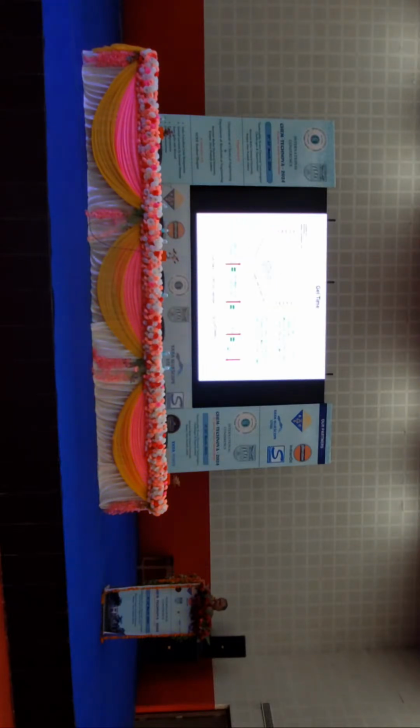Next one, please. Here we obtain gel time, when the phase change is happening from liquid state to gel state. You can see that when the catalyst proportion and accelerator proportion increase, the decomposition of peroxide, which is the catalyst, increases, and the crosslinking increases, because of which the gel time decreases. So we have modeled gel time as a function of accelerator volume and catalyst volume.